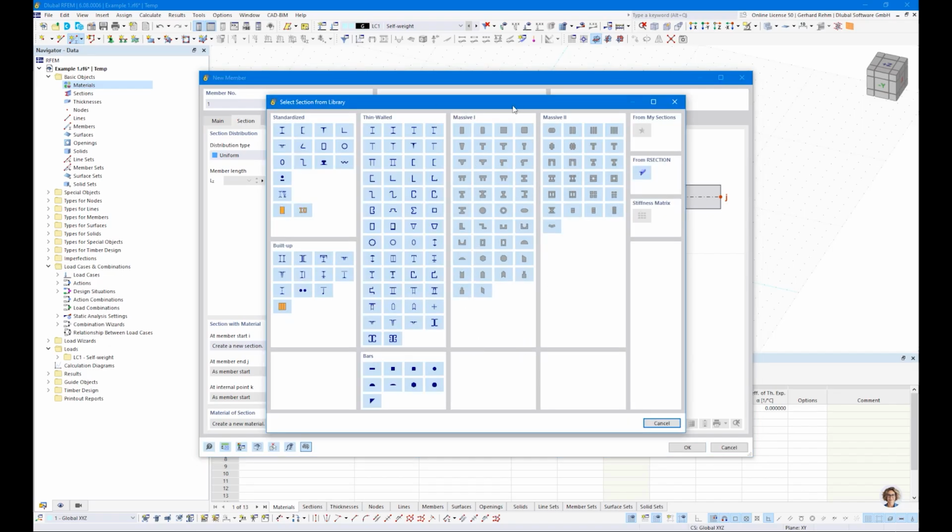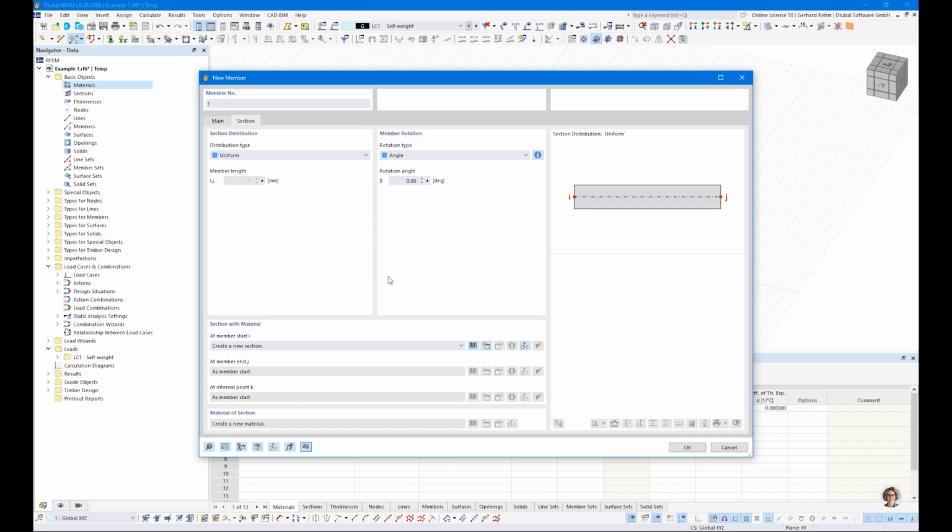All these Massive 1 sections can be designed according to Eurocode and also according to SIA and I guess the NTC. The composite sections, Massive 2, is in progress, so it's not available yet in RFEM 6, since we introduce a new philosophy to design composite sections, because we do not want to use the gamma method, which is described in Eurocode 5, which is really limited in its usage, and we will use a different approach here, and we are working on it. But mostly we use our rectangular section.